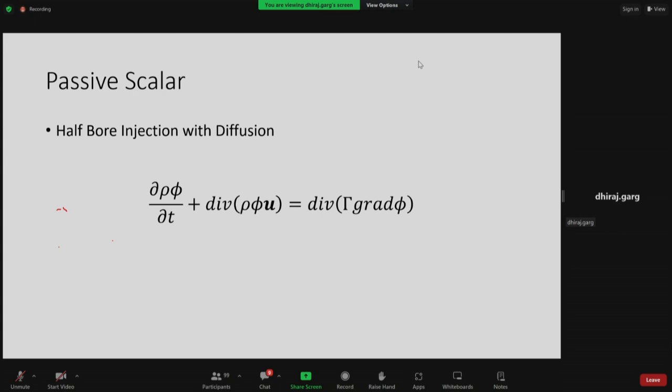And the second is from Sibin. If we are giving continuous injection at a point in a flow field, eventually the tracer will cover the entire flow field, right? Exactly, absolutely. This exactly is the point in the RTD, residence time distribution. So the moment it covers the whole channel completely, you will get phi equal to 1 throughout the cross section, and that's where you need to stop your RTD analysis. So that exactly is the point.